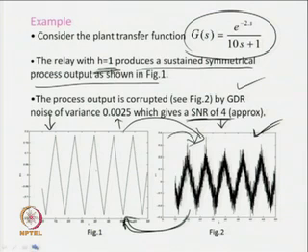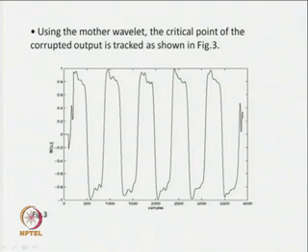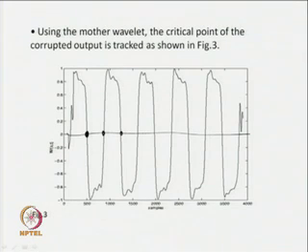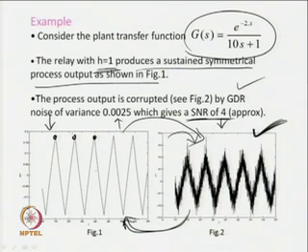Okay. Now, when the wavelet transform of this is taken, what type of output we get? This is what we get. So, if you look at this, then the peak of the output signal are here. Okay. So, basically the peaks corresponding to these peaks will have these zero crossings. So, the period can be measured easily, because if you measure from any peak to peak, you do get information about the period of the signal.